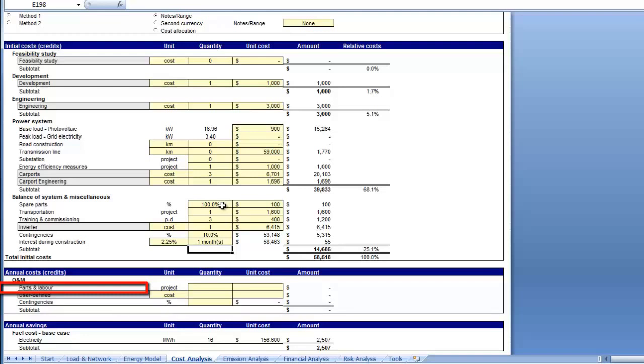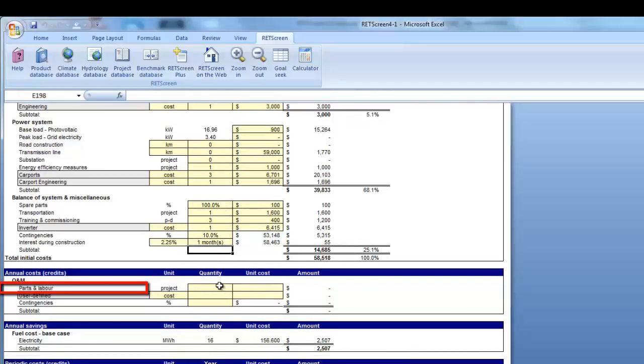Some sources estimate typical O&M costs for large-scale projects around 1.5 cents per kilowatt hour per year, and RETScreen suggests a range of $0 to $200. At 1.5 cents per kilowatt hour per year, we get an O&M cost of $168, which falls within the RETScreen cost range. Although this rate is typical of larger scale systems, we will use it assuming that paid technicians would conduct the annual inspection and may require travel and labor costs.